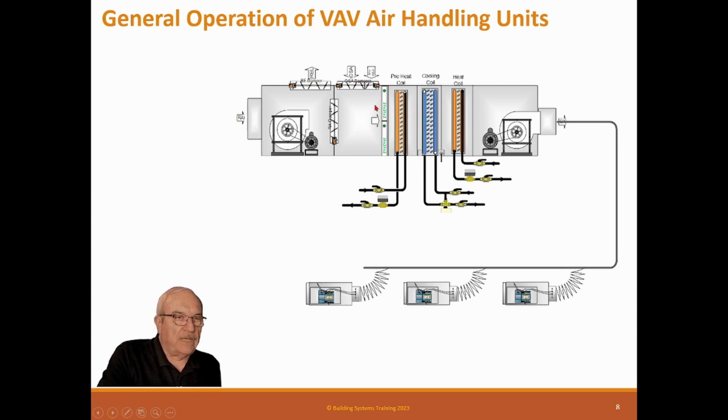This has a full economizer and it has a return fan. Now, not all units have full economizers and not all units have return fans. It may have an exhaust fan and a relief damper. I prefer return fans over exhaust fans. They're actually easier to balance.